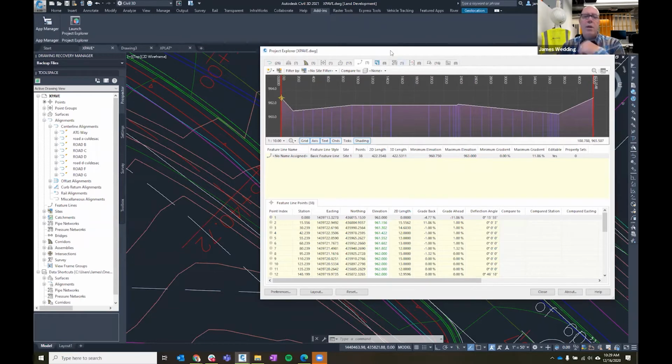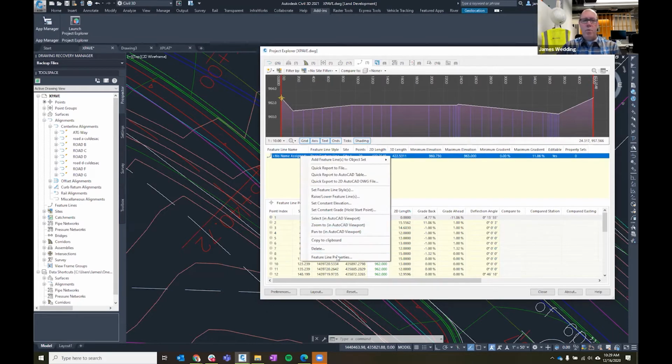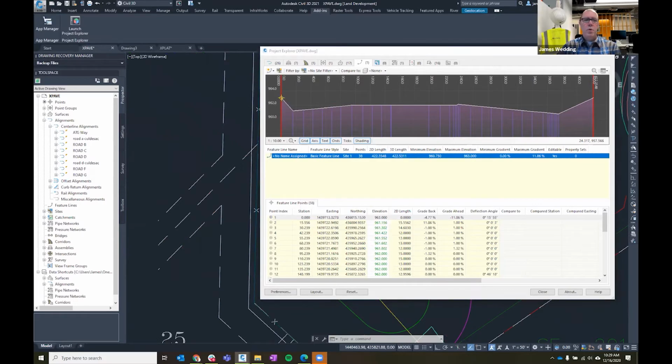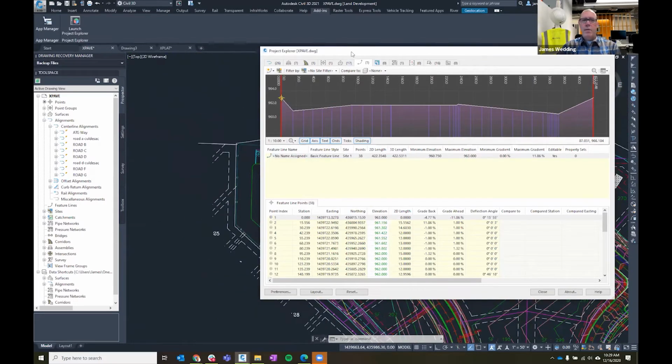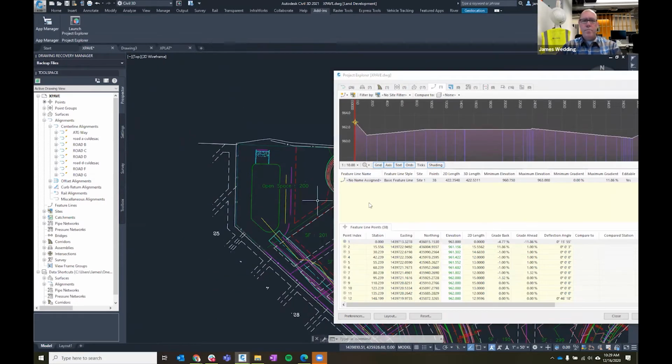The last thing I want to look at before I jump into reports is this idea of working with the comparison. A comparison allows us to create a temporary view where we're comparing 2 different objects, and then can use that to help drive our design. So this is a feature line that I've got up in this north area. So again, zoom to, and we will pan and zoom to get where it's going.